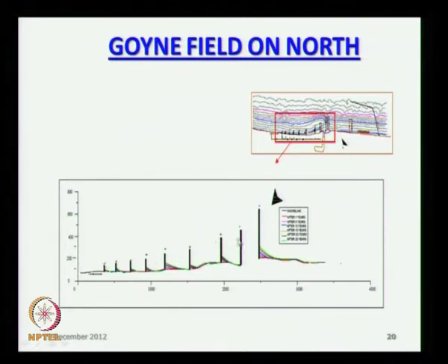The length of the groin typically reduces as you go towards the north, and the spacing between the groins is proportional to the length of the groin. Typically the spacing between the groins is about 2 to 4 times the length of the groin, but you have to do some model study. Over a period of time, after 25 years, the shoreline advances like this. Actually this has happened in Chennai port. I will show the satellite imagery of how the shoreline is advancing.